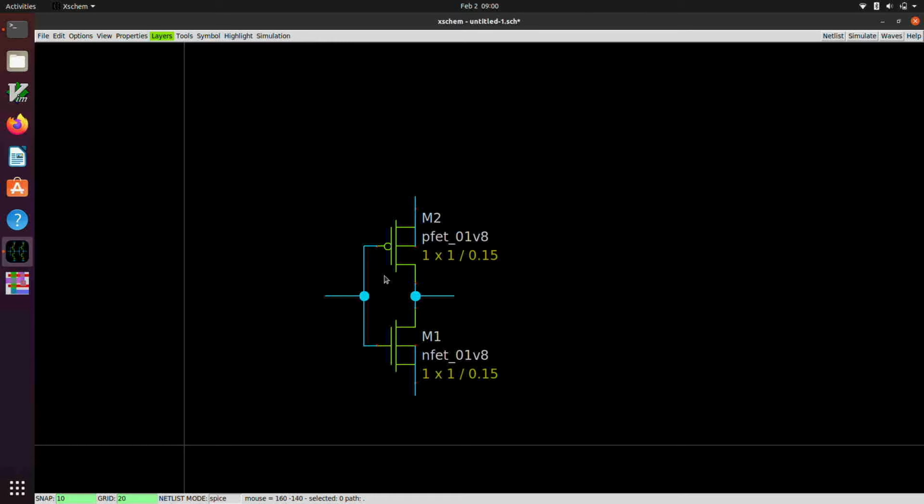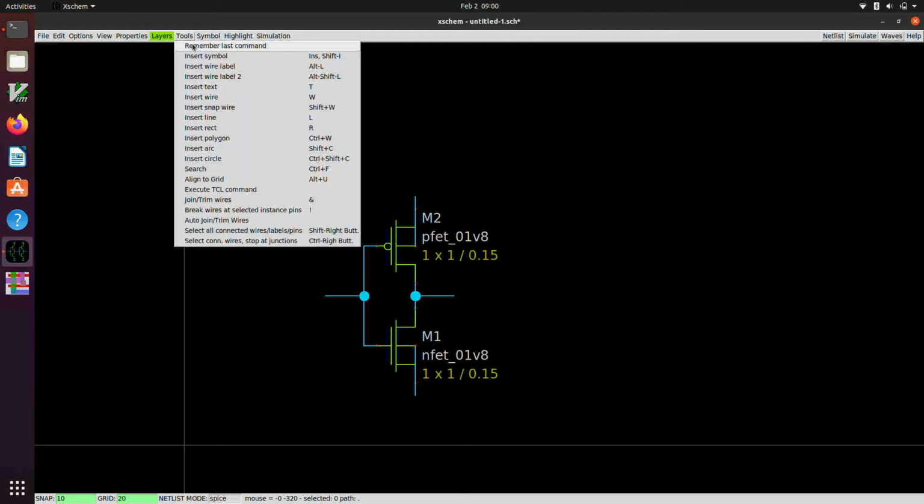Sometimes you'll see me propagate the power supplies into a subcell explicitly, but use 3-terminal MOSFET connections because I don't want to have the 4th terminal running around because of the way I make my schematics. And so you just have to be careful. But in this particular tutorial, we're going to explicitly put in the power supply connections as terminals in the symbol that we create. So we're going to need to get some pins, and